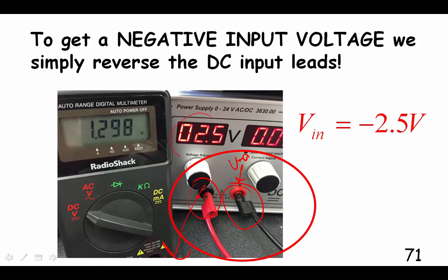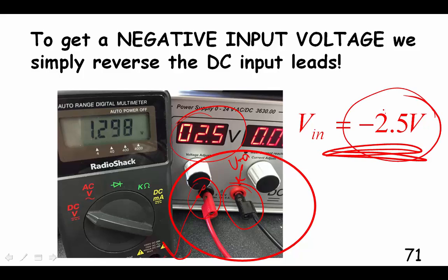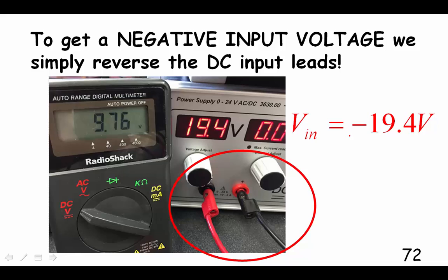So our negative terminal of the power supply is now going below that. So then when I read 2.5 on my power supply, it's really giving out a -2.5 to my breadboard in reference to its ground. So I'm putting in -2.5, and if I have a gain of -1/2, then I get a positive voltage out of the op amp, which is right, and it's about half of that. So now I just have done 2 of them now.